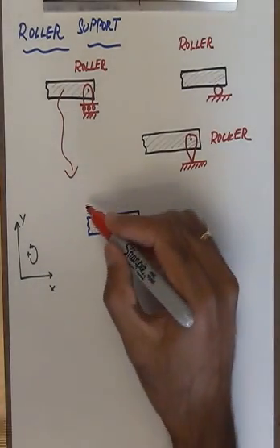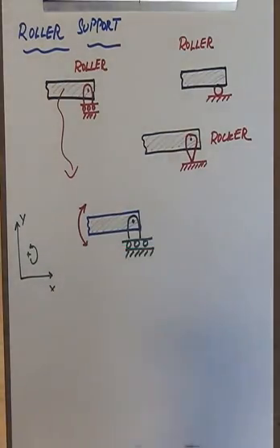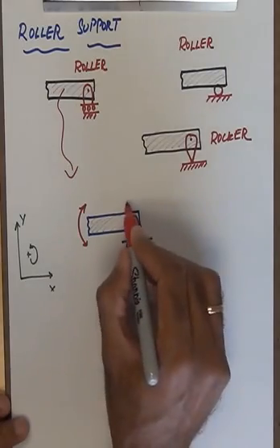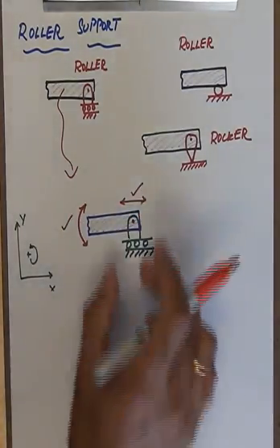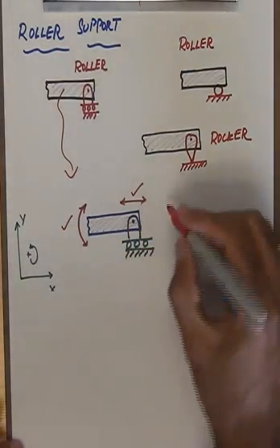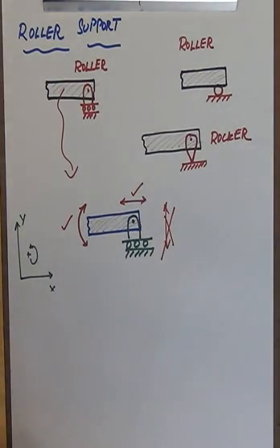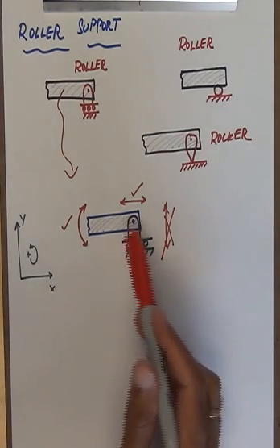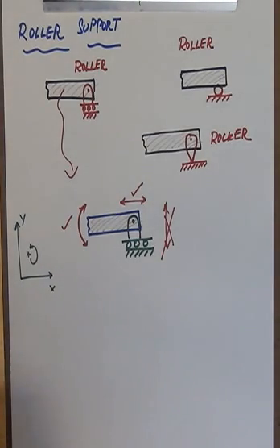You see that here I can rotate it in the clockwise or the counterclockwise sense about the positive or the negative z direction, which is coming out of the board. Also, it is possible for me to perform a translational motion. So these two are possible for me. You see that these are a set of wheels here, right? Which means that I can move them back and forth here, but I cannot move it up and down. So that kind of a motion is not possible, and that is a unilateral constraint, in the sense that in reality I can have this roller lifting off of the ground, but then I cannot sink into the ground further. And so that's a unilateral constraint.